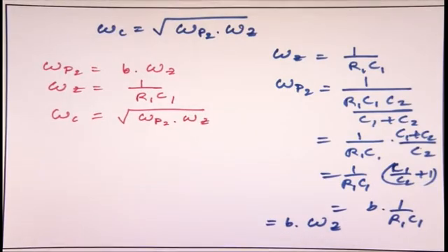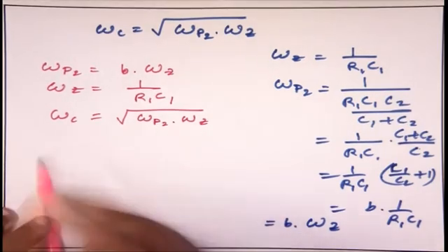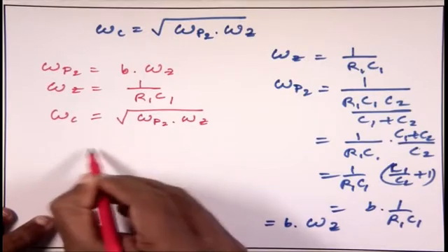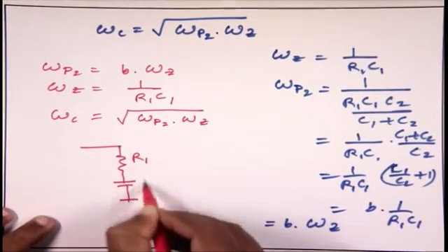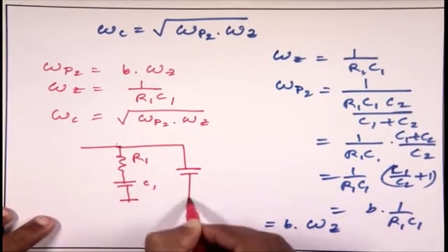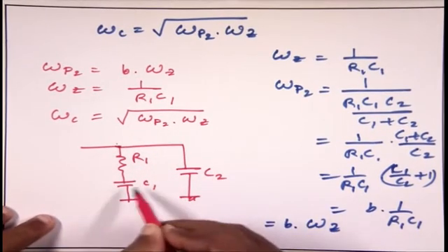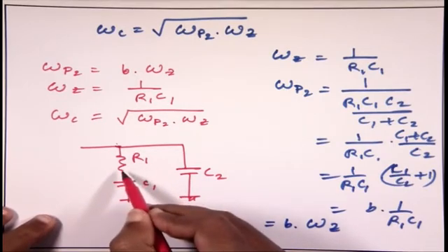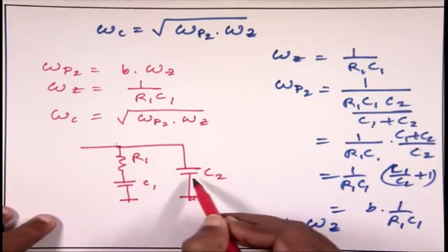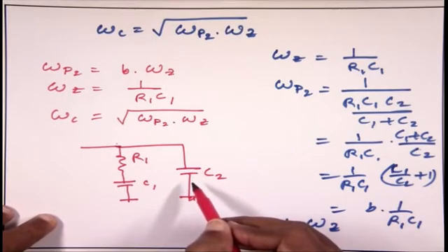Now let's start talking about real values. Again assume that the loop filter is R1 and C1 with a parallel capacitance C2. Why is C1 there? Because C1 is the main filter. Why is R1 there? Because R1 is the zero-creating factor, so that the function will be stable. Why will C2 be there? C2 is there to reduce the ripple at the control voltage.